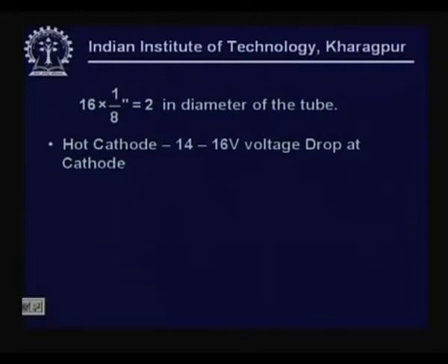And here, remember, this is still a discharge lamp which would expect a discharge in a gas, and recall it is the low pressure mercury vapor lamp. Now, all gas discharge lamps depend on electron emission. The processes that are responsible for electron emission are thermionic emission, electric field assisted emission, and photonic emission or impingement of light.